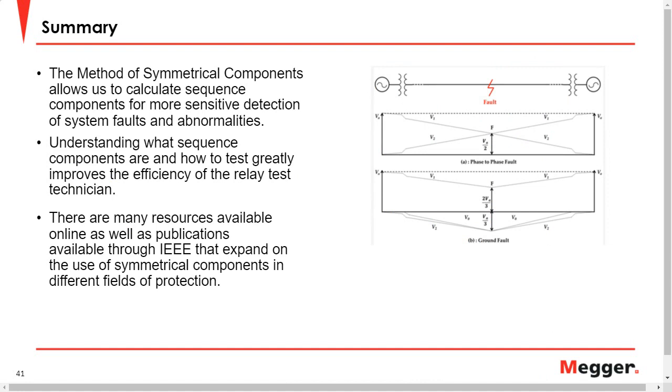So lastly, in summary, the method of symmetrical components allows us to calculate sequence components for more sensitive detection of system faults and abnormalities. For a technician, understanding what these components are and how to test them greatly improves the efficiency. It makes it much easier to test these elements out in the field.